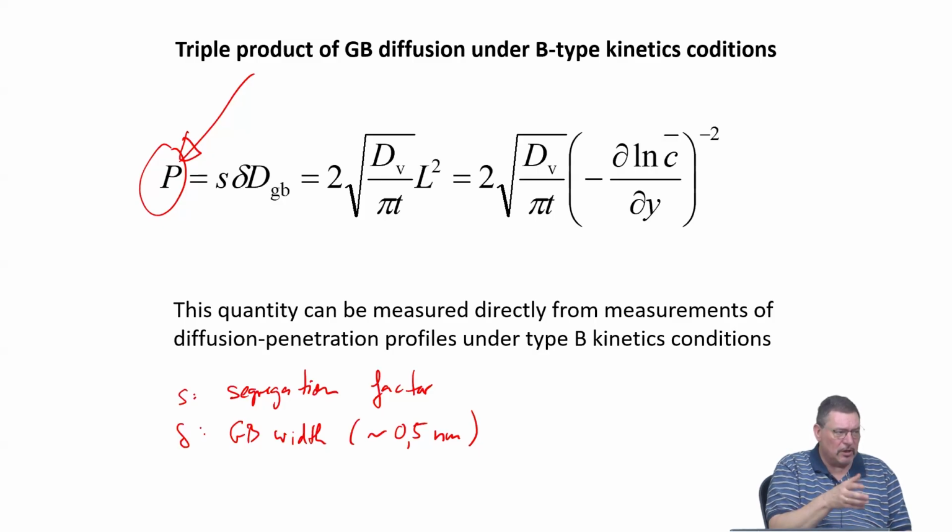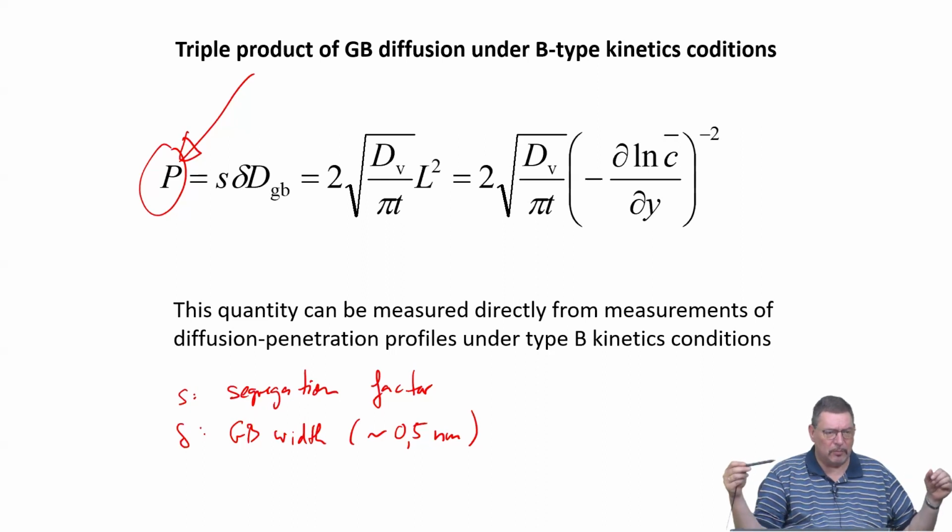Because when you look with atom probe tomography, this is a method you know, you have a very small tip which has a radius of curvature of 10-20 nanometers, which you prepare of your material. And you apply it now at low temperatures into a very strong electrical field with electrical field gradient. So basically you field evaporate atoms from your tip.